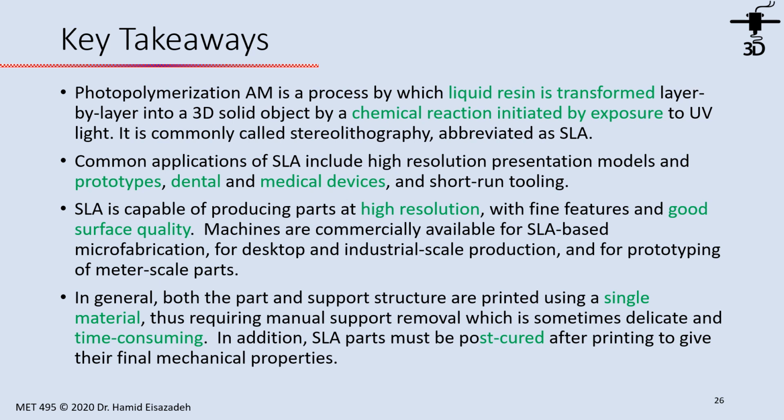SLA has high resolution. It can deliver fine features with good surface quality, compared with the extrusion AM process. In SLA, we need a support structure, and it has to be printed from a single material.